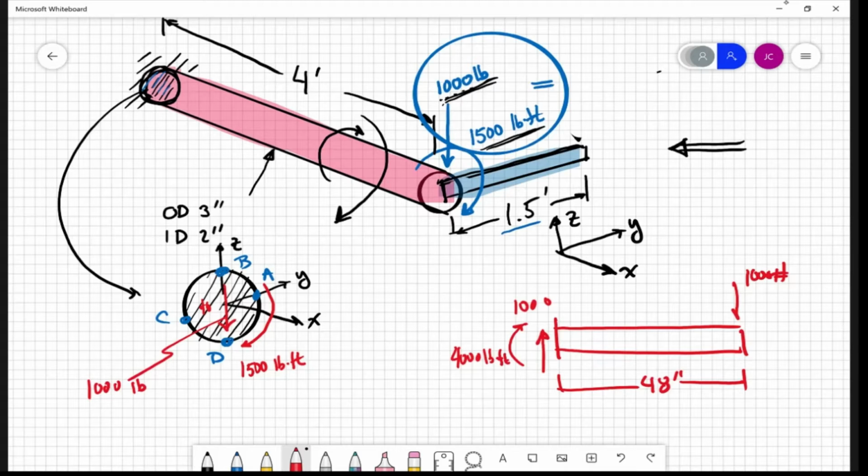All right. And this cut face here is just on a little differential segment, just a little bit to the right of it, the way we're looking at this. So that's why the shear force is acting down instead of acting up, right? So we're actually on this face here. Okay. And so we've got the shear force, we've got the torque, and we also have this bending moment.